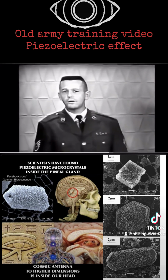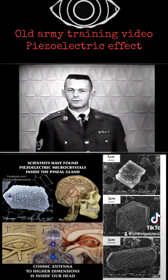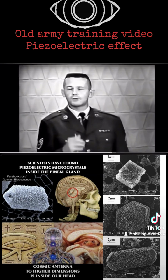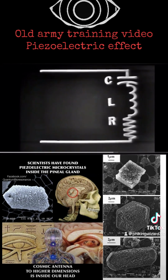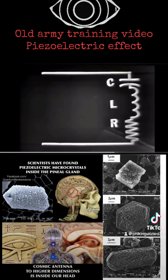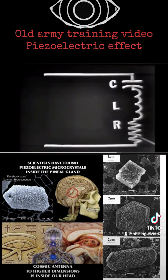Now so far we've seen the physical characteristics of the crystals. Let's now see how the crystal reacts electrically. To do this, we'll look at the electrical equivalent of a crystal and its holder. The crystal itself, when vibrating, acts very similar to a series resonance circuit containing resistance, inductance, and capacitance. Remember, this is when the crystal is vibrating.